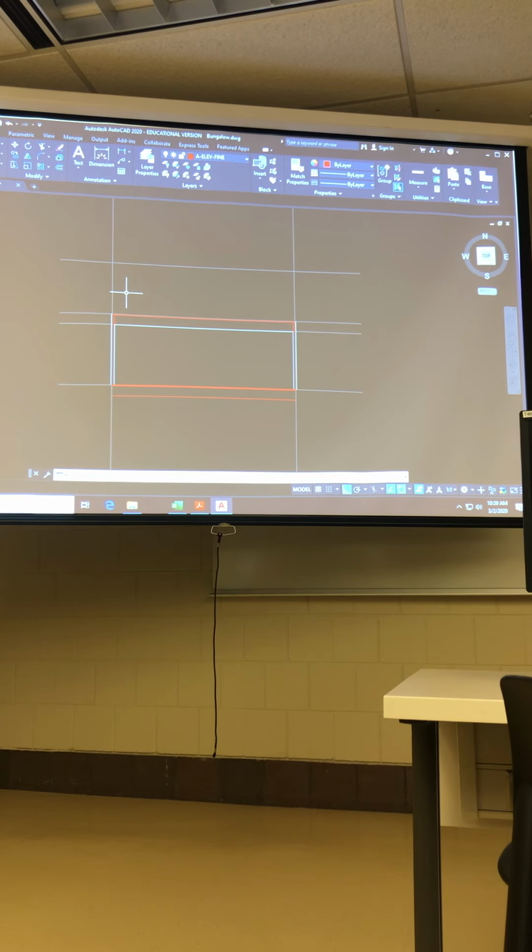So what I'm going to do next is start drawing the slope for my roof structure from that work point. And the way I do that is I'm going to enter L for line. I'm going to pick that work point right here. And now you may not have used this string of commands yet, and I'll show it to you a couple of times so that you see it. But it's a way of drawing a line that has a specific horizontal distance and a specific vertical distance, and it is a miracle for drawing roof slopes.